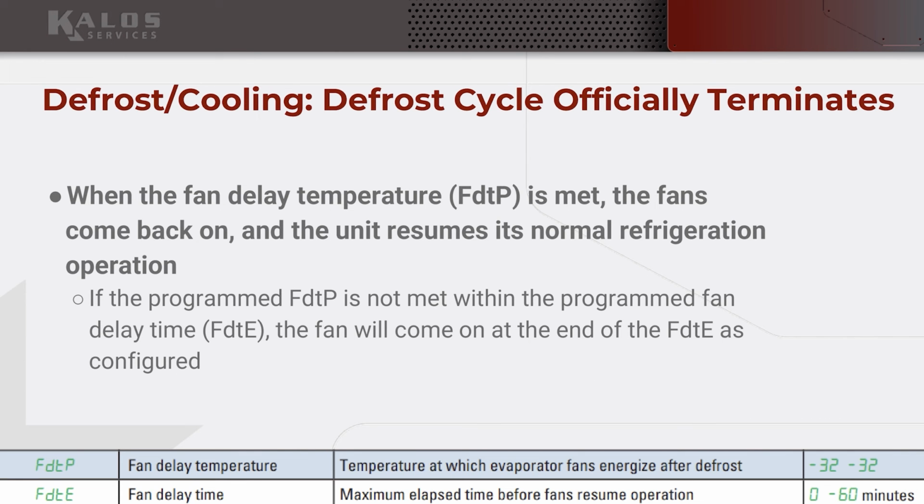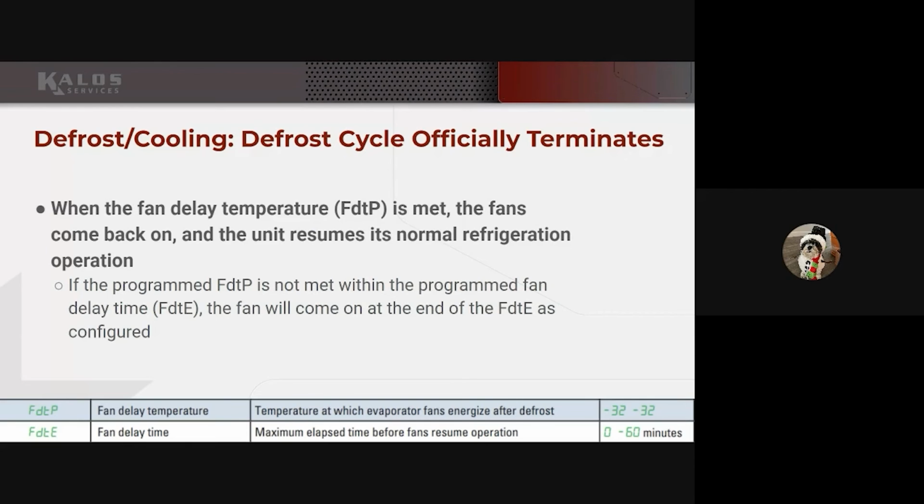Okay, so we finished our defrost cycle. Now fans are going to come back on. When the fan delay temperature is met, the fans come back on and the unit resumes its normal refrigeration operation. As you can imagine, now we're not running defrost. We're simply providing power to the fans and the compressor, and things are going to operate as they should.